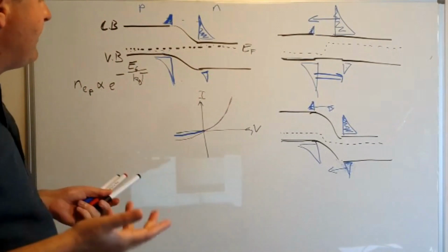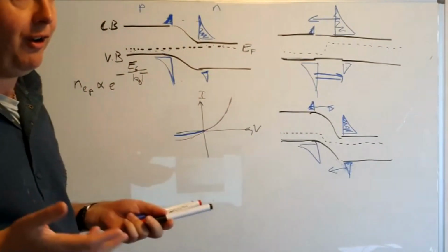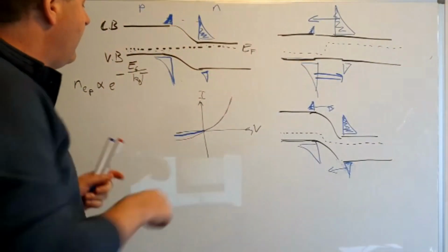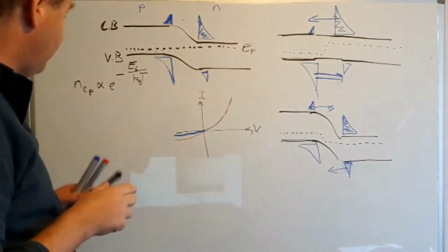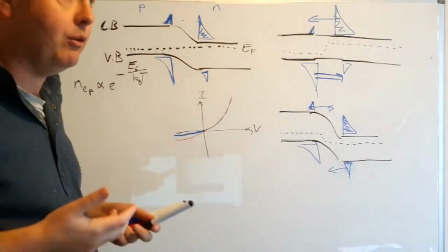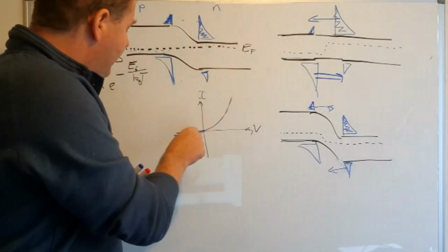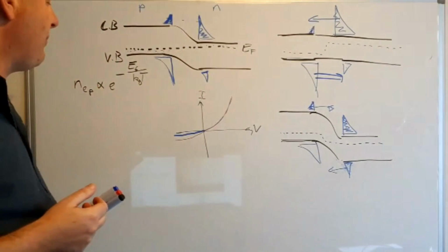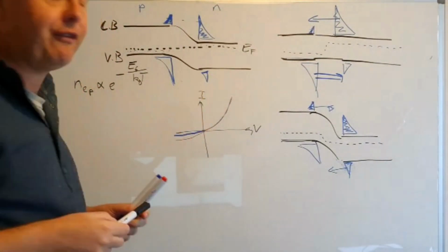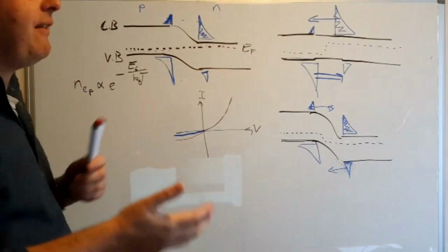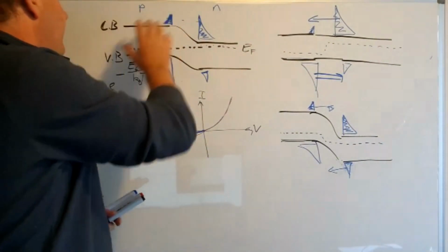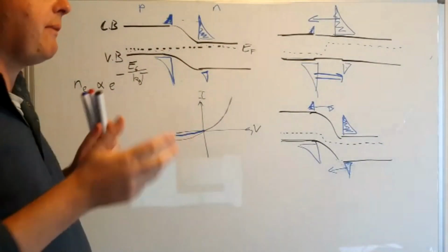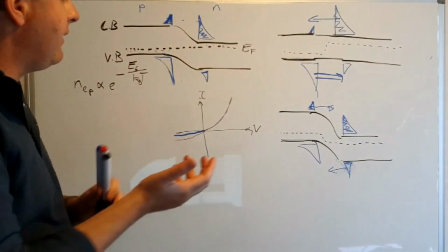So there are two limits where it's going to stop working. One is if it gets very, very hot, then I'm going to have lots of electrons being promoted over here, and eventually it's just going to get to the point where I've got too much current flowing through my sensor. On the other hand, if I get very, very cold, then this current goes to zero, and it gets very, very hard in practical terms to actually do a measurement because I get a voltage and I get no current flow. So again, there's a limited working range of this, which is determined by the actual underlying physics of what's going on. So let's look at another couple of types of temperature sensor and discuss how they can be useful.